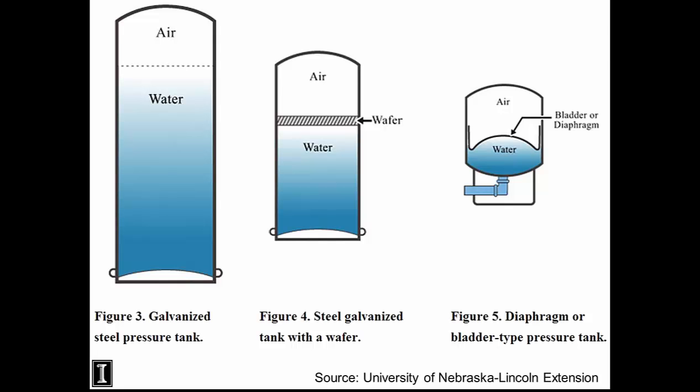And if you don't add air, all of a sudden your pump starts kicking on and off regularly because there's not enough air in there to cause a pressure difference. Because what you're doing when you add water to those tanks is you're compressing the air, increasing the pressure, and then it's the air that's pushing the water back out whenever water is needed in a faucet or whatever. And so they require more maintenance.